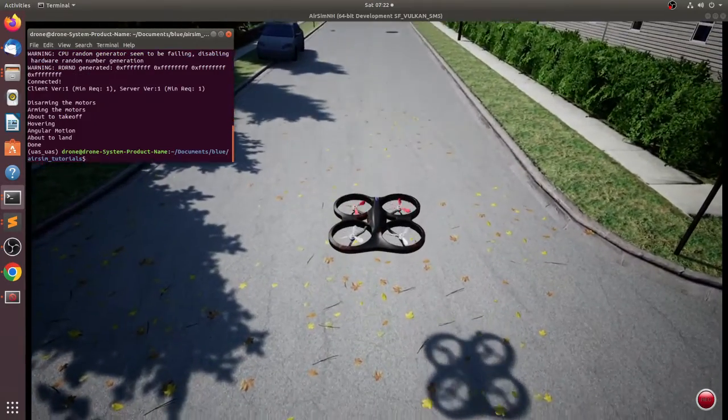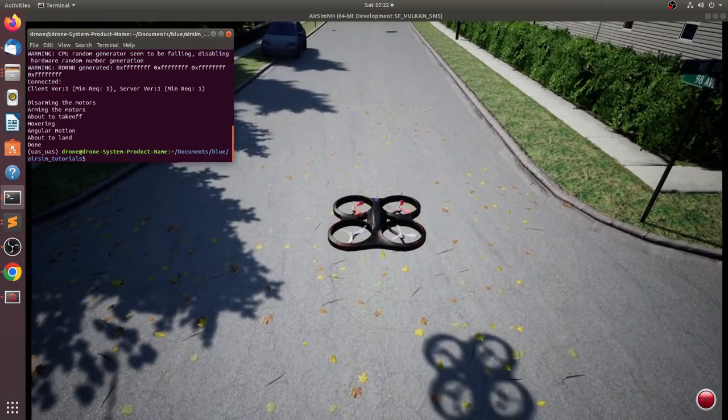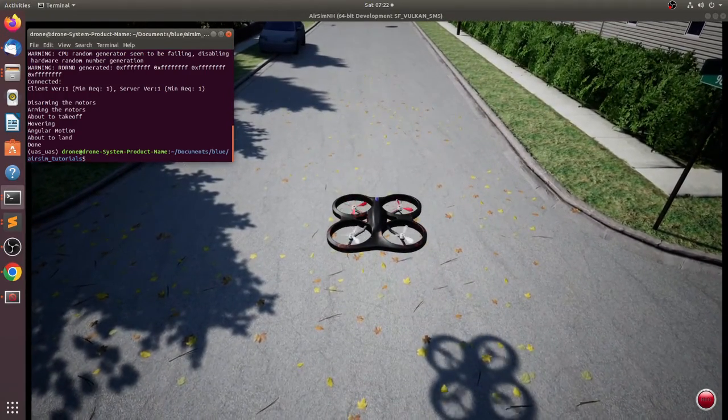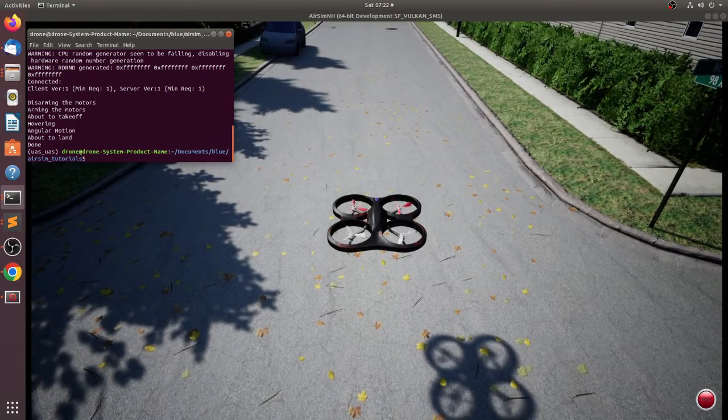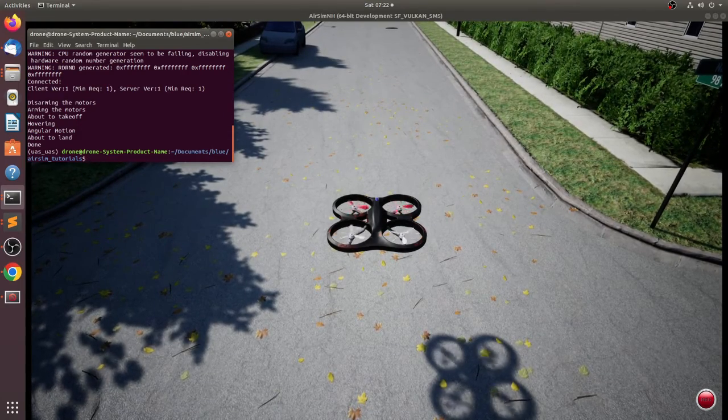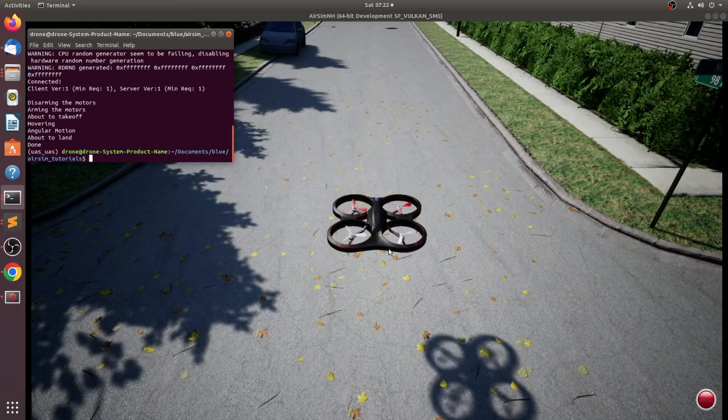You can see that it performed the roll, pitch angle. And you could also see that when we give the pitch angle here, it has a displacement along the x-axis. Did you see that? It moved a certain distance, right? We're going to cover why it did that in the translation motion. This is how we achieve the translation in the UAV, by changing these roll pitch angles. We'll cover those in detail in the next tutorial, but for now be aware that it causes the translation motion.